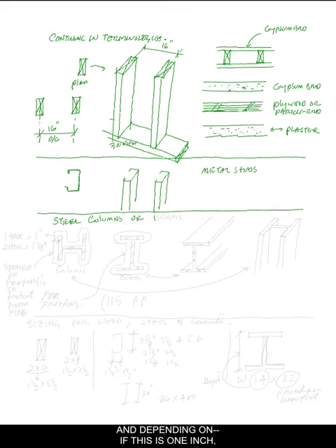And depending on if this is 1 inch, you get 1 hour of protection. If it is 1 7/8, you get 2 hours of protection. You see that type of diagram on page 115. And that's how it is shown.